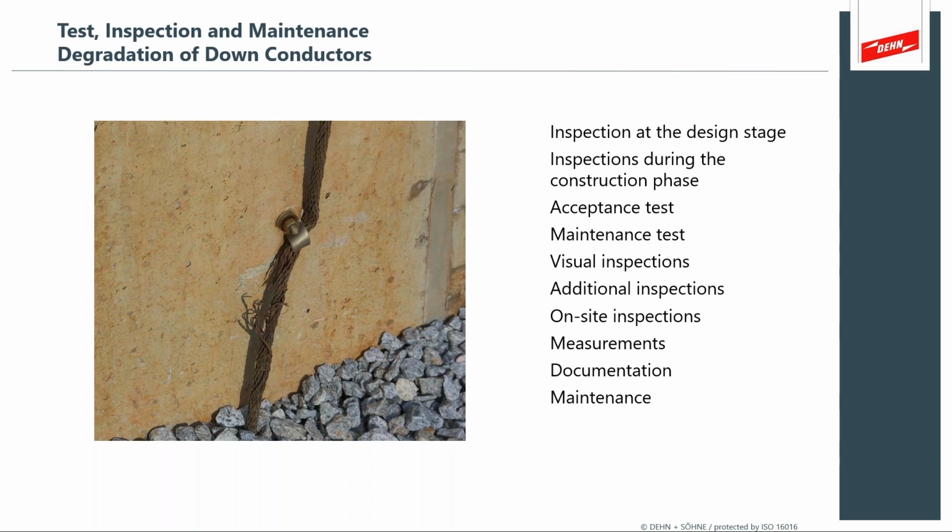And I love this picture of a frayed pigtail bonding into the lightning protection downcomer, because it shows you what you really need to watch for, because this is going to be a real problem. And of course, all the way through final master label certification as needed for your applications.